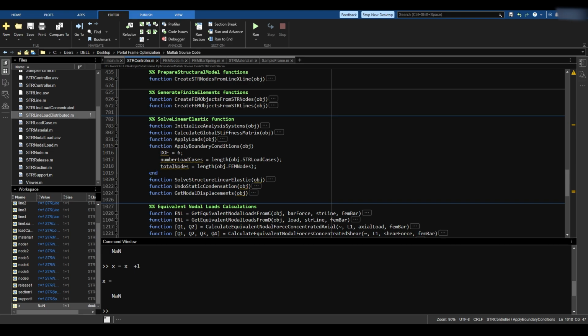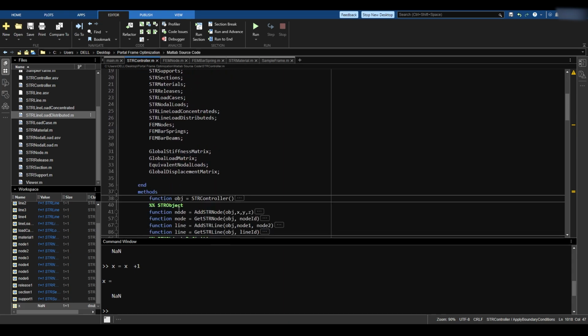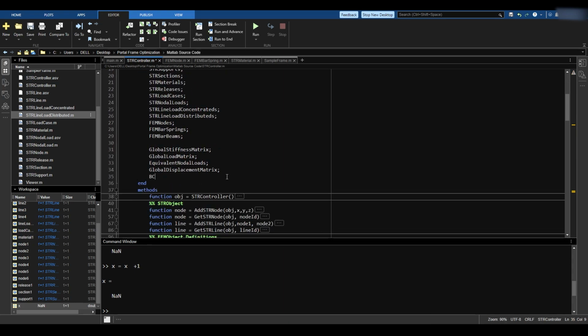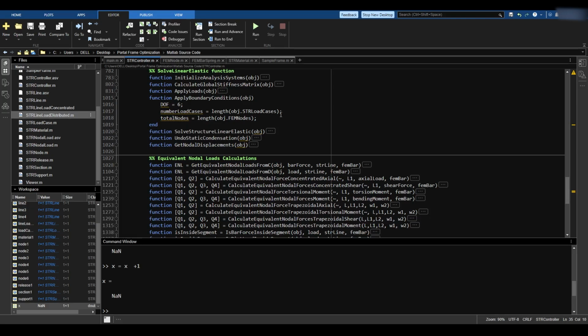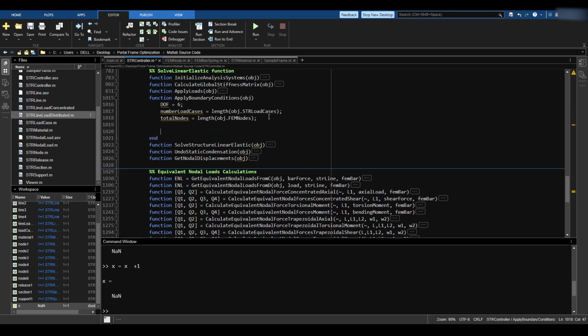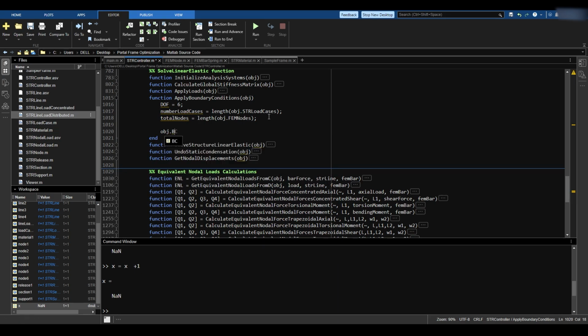Since I have boundary conditions, I must find a storage system to store them. So let's go to the storage and give us here a storage for the boundary condition. I'll call it simply BC. So BC is a vector that stores the boundary conditions. By the way, you could program boundary conditions of Neumann and of Dirichlet, meaning force and or displacement boundary conditions. I just use the boundary conditions in the typical sense, where I apply a pin and the displacement is 0. Let me initialize my boundary condition, so I'll go for object.bc.